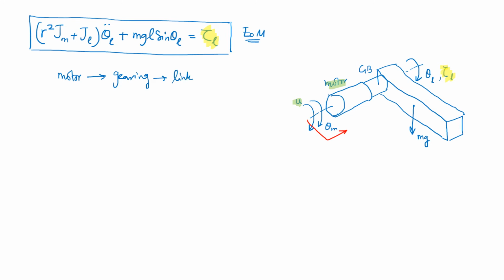So in that particular case, actually the process is that the link torque is going to be equal to the motor torque which is available minus the damping available in this whole arrangement, and this damping is going to come partially from the gearbox as well as from within the motor where you have bearing surfaces available.